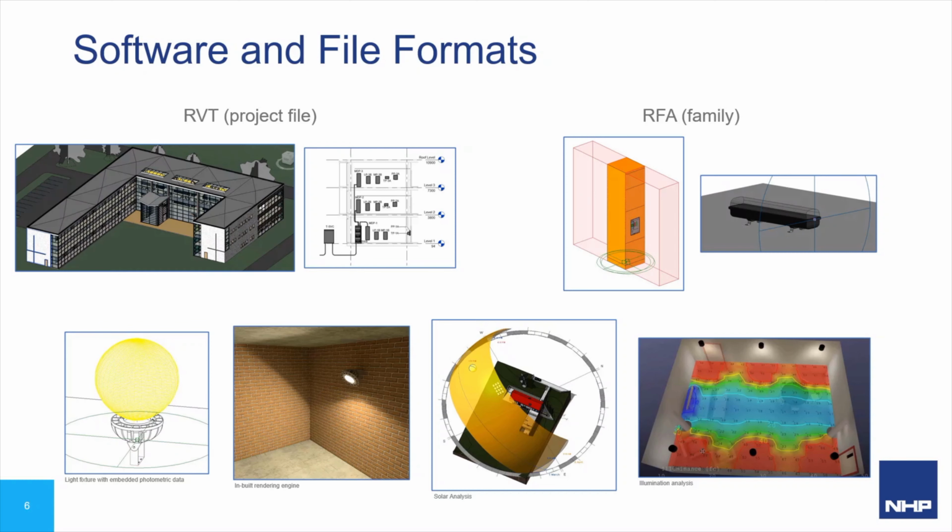You can import and export some foreign CAD files for the software environments we mentioned earlier into Revit. Exporting a Revit family to, say, a 3D file, for example, is indeed possible, but at the expense of any embedded information within the family. It would no longer be a BIM object. The term BIM object being a more generic term without needing to refer to a proprietary file format such as RFA or RVT file. Importing a 2D or 3D file into Revit is a straightforward task.